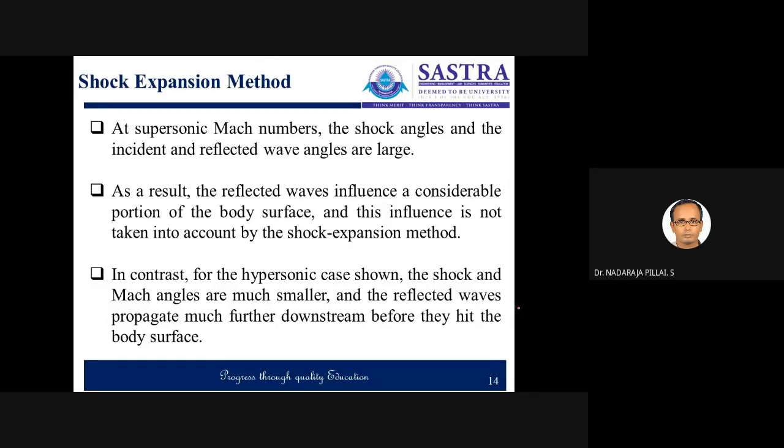So we can say that at supersonic Mach numbers, the shock angles and the incident and reflected wave angles are large. As a result, the reflected waves considerably influence the surface, and also considerably influence the pressure which we measure at the point I on the surface.